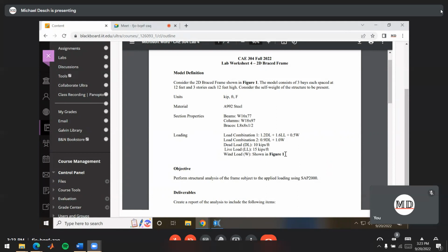Now, when we're designing our building to make sure it handles all the loads, we find the maximum amount of load we want it to handle in all those cases. We can pull that from a code like ASCE 7. And if we just say, I need it to withstand all this dead load, all this live load, all this snow load, all this earthquake load, all this wind load, everything all at once, that'll work.